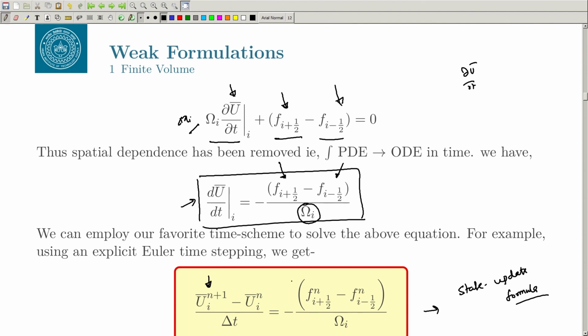So, this right hand side term is called the residue. Okay. If you use Fluent or many different solvers, you would be looking at how the residue is going down, right. Basically you say that if it has gone down to 10 to the power minus 4 or minus 5 or minus 6, then your solution is converged, right. So, what is happening there, let's understand here.